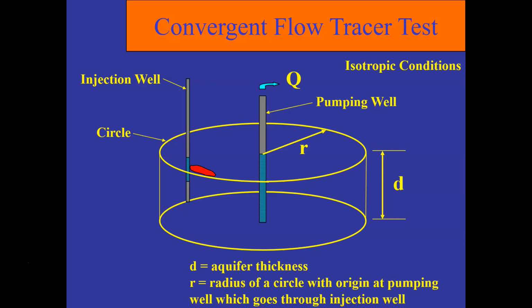And I think it was Terzaghi who said, if you know nothing about a hydrogeologic formation, assume it has a vertical anisotropy of 10. Most formations, certainly sedimentary formations, alluvial formations, are going to have a vertical anisotropy of probably at least 10. When we're doing mathematical modeling, we put 10 in as a routine number. And if we have better data, we'll change it. But usually 10 is the default value for vertical anisotropy.